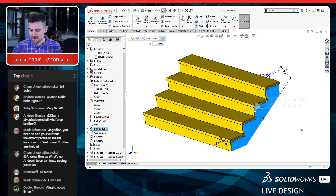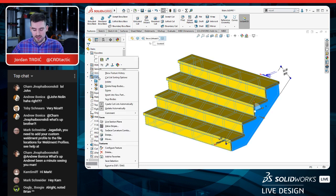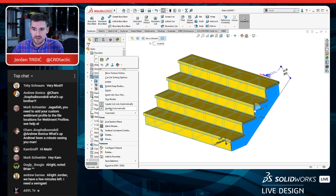It's because this is nothing more than an extrusion. And if we take a look at our cut list in here, by the way, this is automatically working because I've selected from the right-click menu, Update Automatically, and I save that into my part template so it always behaves that way.